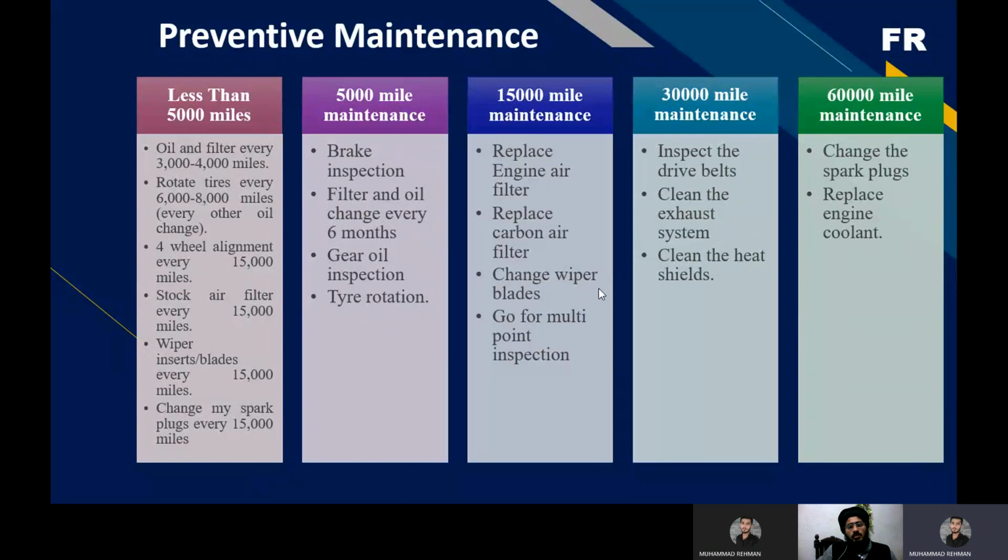And after 60,000 miles you have to change spark plugs, because of the burning of a lot of fuel and other things. Basically our engine is Wartsila, so there is no need of spark plug changing. And we have to see the fuel injectors. And similarly after 6,000 miles you have to change engine coolants. This is roughly the estimation on the basis of average data collected. You have to keep observing all the components. If any component gets a problem, you have to repair it.